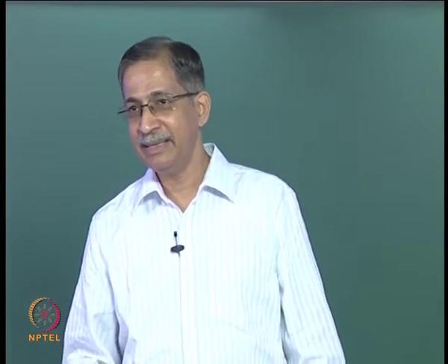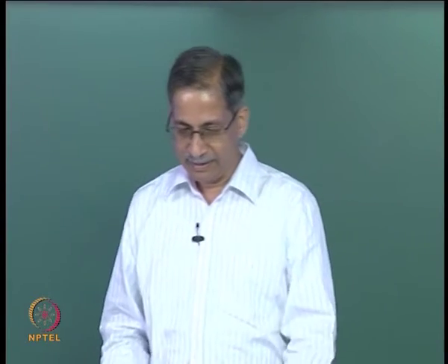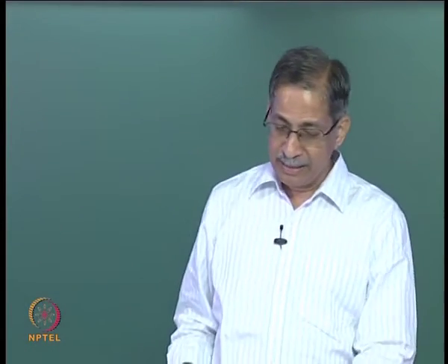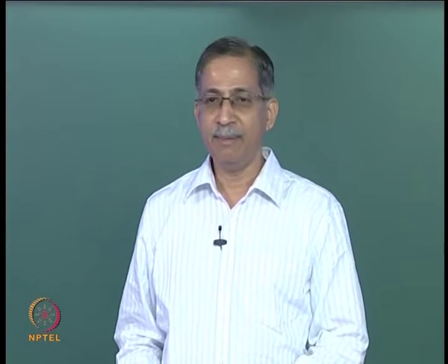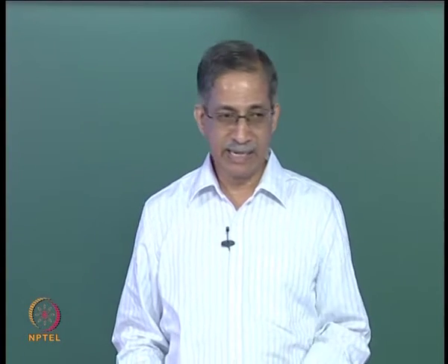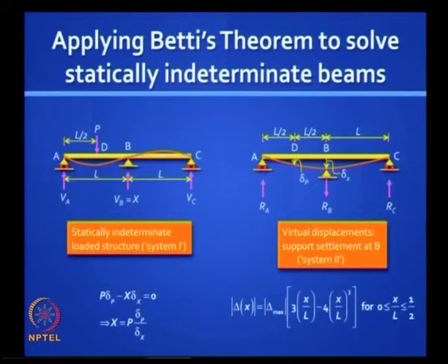So it is a simple initial way of understanding indeterminate structures, and if you really had an exact solution to those deflections, and you can derive those by any of the methods that you know, including direct integration, conjugate beam method, virtual work method, if you have an expression for delta X and if you plug in the value of X equal to L by 2, then you can actually get the exact solution, which in this case turns out to be 11 by 16 P.